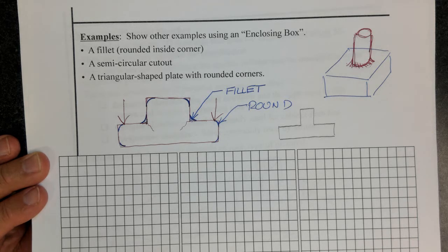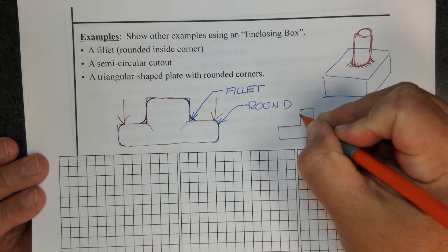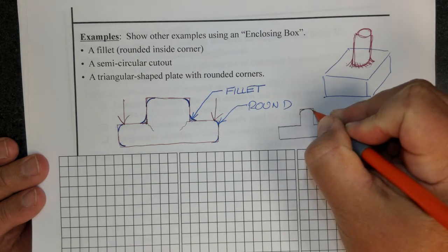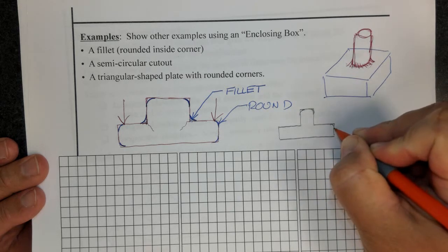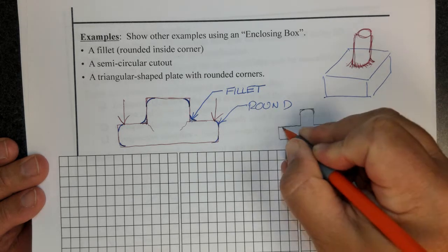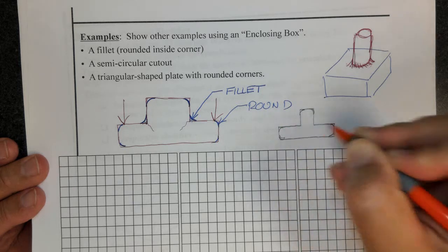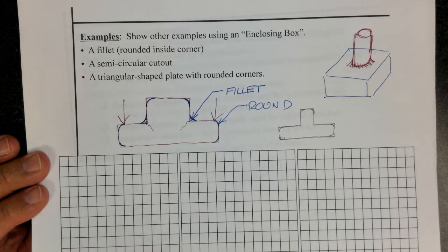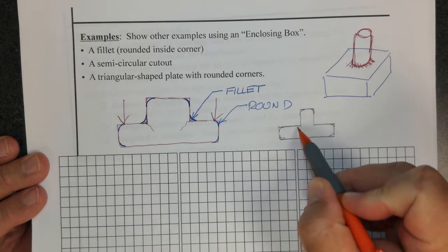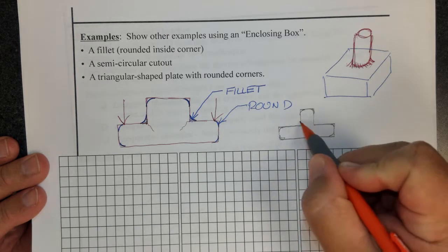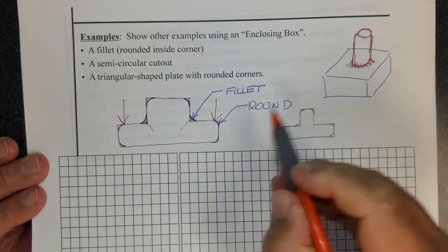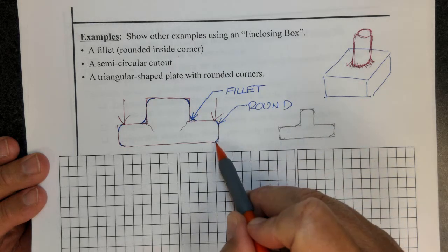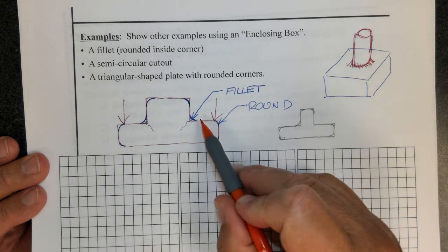You need to design it in such a way that it's safe to handle. These are sharp points. So if you don't need the sharp points, sometimes it's best to put in a rounded corner. Okay, a rounded corner here, and then here, here. Okay, so another thing is the internal corners. Sometimes it's best to put what they call a fillet. And by the way, I have them labeled here. The external corner is called a round, the internal corner is a fillet.